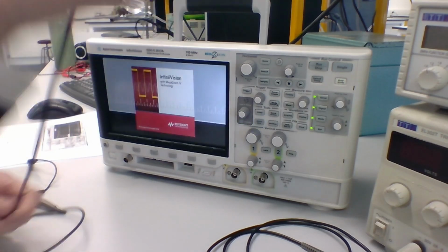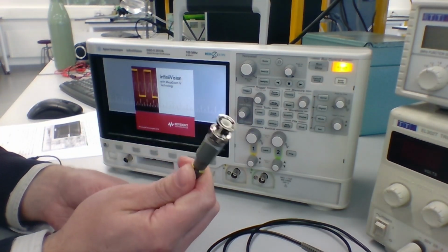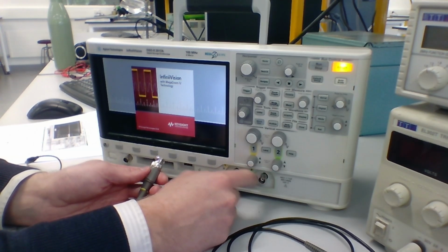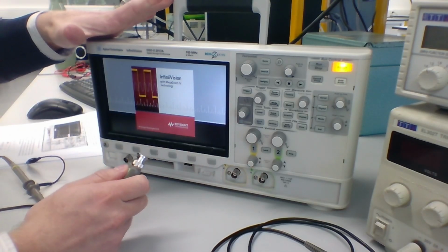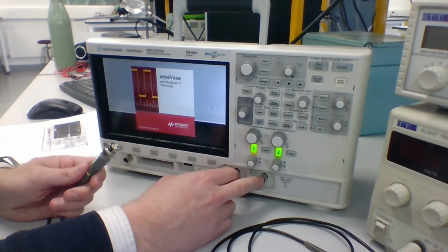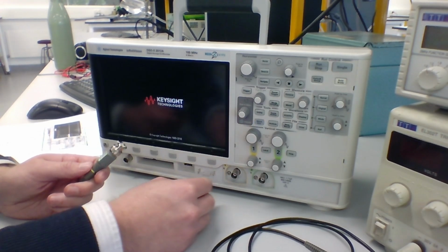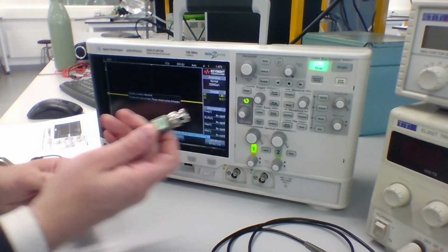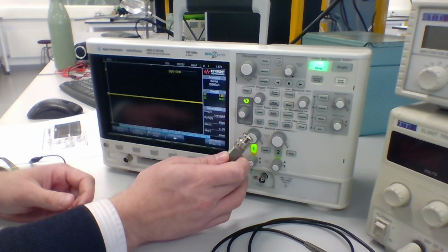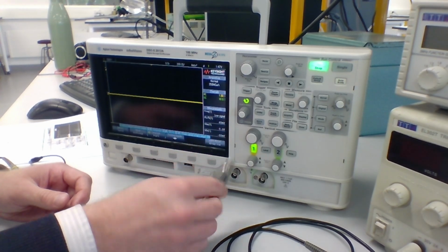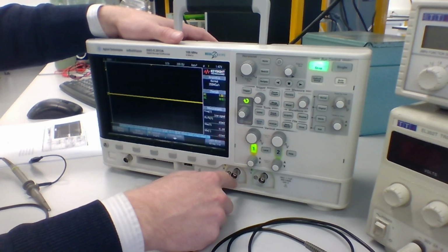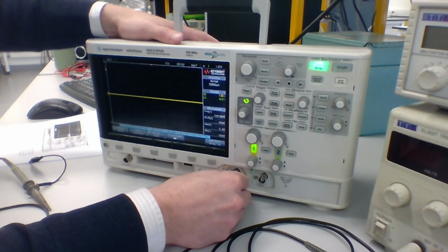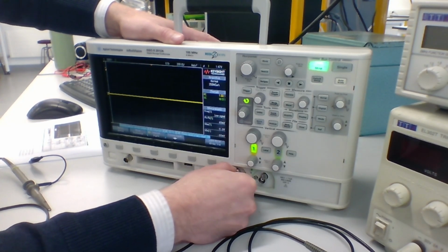To connect these to the oscilloscope, we take this BNC end here, and we connect to, on these oscilloscopes, one of these 2 ports here. We call this a 2-channel oscilloscope because it has 2 separate channels we can use to make measurements. Other oscilloscopes will have more or fewer channels. To connect this to the oscilloscope, what we do is we take the BNC end and we slide it onto the port here. And you'll feel when it slides on, you'll need to rotate it a bit to line it up. Slide it all the way in, and then we rotate it to lock it in.